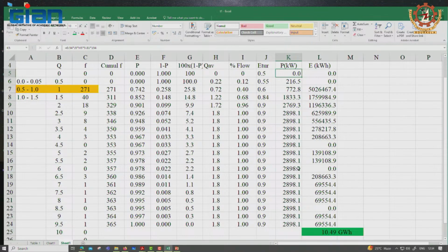Assume this 2898 is 3000 and put 1500 into 2, take the first machine to the maximum power, 1500, and then start the second machine. Here you will have to restrict it to 1500, and then take the other machine from this point onward.